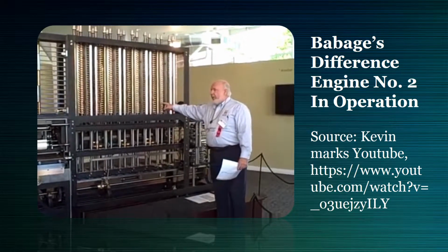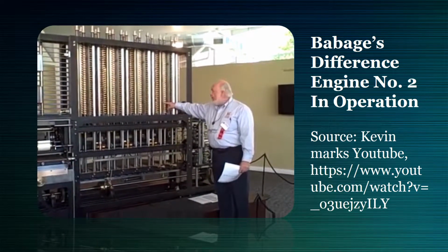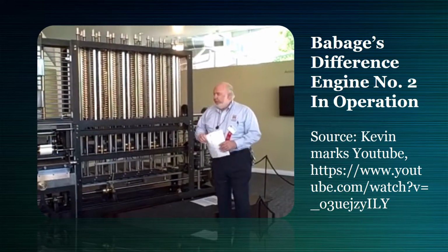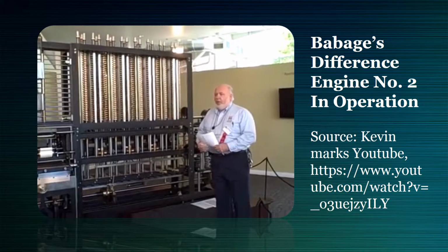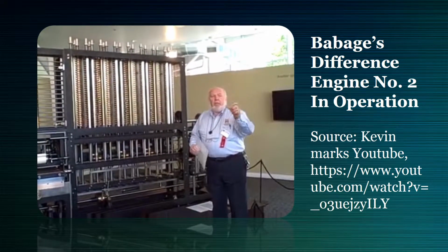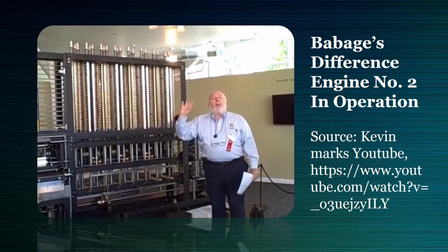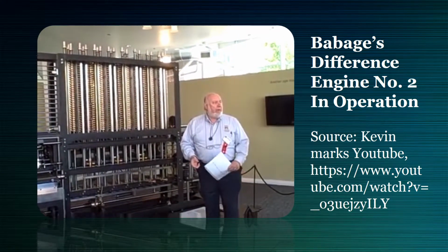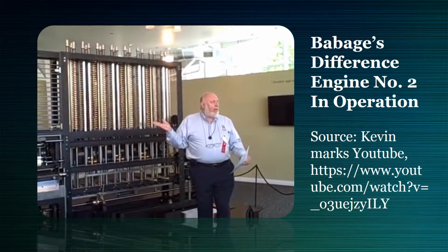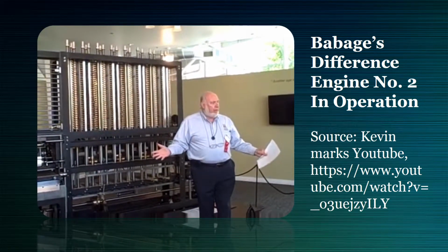Well, it turns out these gears are set up so that they're double thick on one side and single thick on the other. So when they're down touching at the bottom, they're hooked up between the two. But when they go up a little bit, the even side is no longer touching the even gear, but it's still touching the odd gear, and the odd gear will simply get reset. And then it moves up again, and when it moves up again, it's not touching either side. It disengages completely.